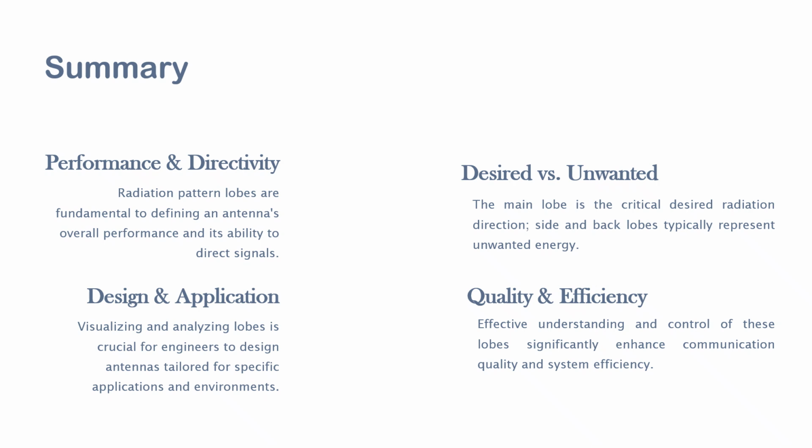From the radiation pattern you can now understand what the main lobe is, what the side lobes are, and what the impact of the side lobes is in the radiation pattern, and how it has to be designed in order to provide maximum directivity in the desired signal.